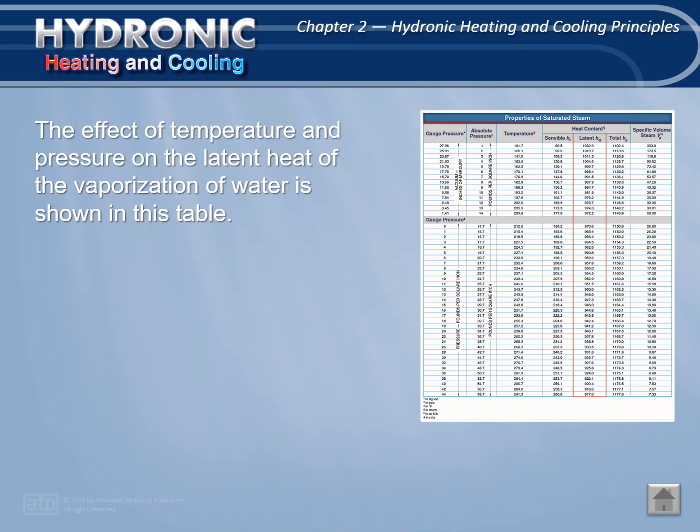On this chart, you can see how pressure and temperature affect the boiling point of water. As you can see, where the gauge pressure is 0, or it's at atmospheric pressure, the boiling point of water is 212 degrees Fahrenheit. When you put it into a vacuum, with the numbers above, the boiling point starts decreasing. And inversely, when you start adding pressure, the boiling point rises.